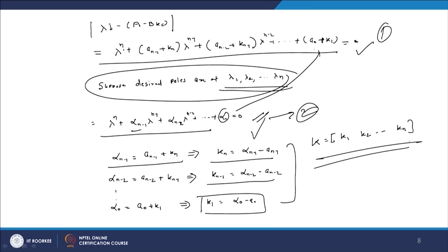So, this controller k will stabilize the system as per our requirement. As far as the simulation is concerned, you can design the pole anywhere, whatever we require; that desired pole placement is possible, desired controller is possible, desired performance is possible. So, we can see the beauty of the advanced control approach, the state feedback approach, where this is not possible in the classical approach. But although I told you that theoretically everything is okay, practically there are some issues. As I told you, we require high quality actuators, even the sensors, because we have to sense. If you are placing the pole far away, the control input is more, and it may cause some problems, that means we require very high quality actuators.